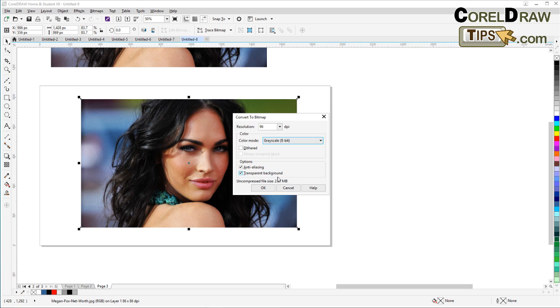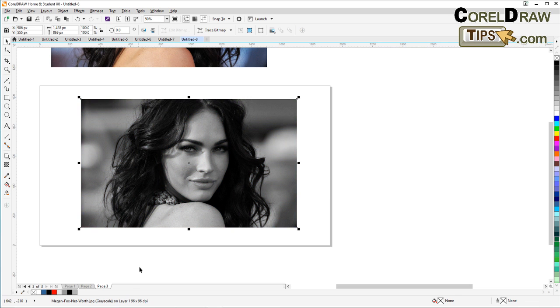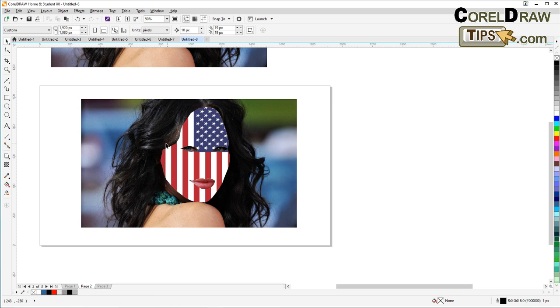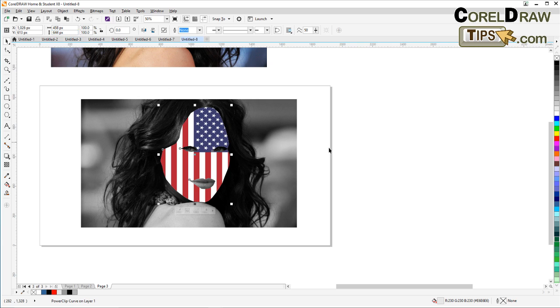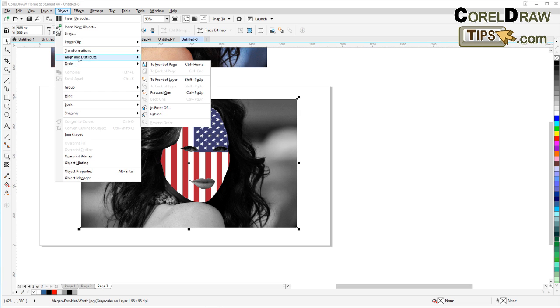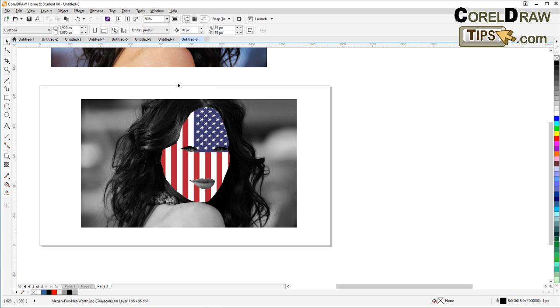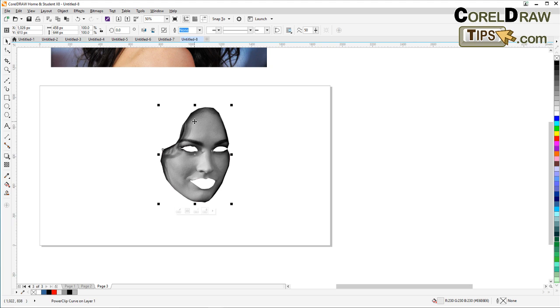But then I'm going to make this grayscale, like you said. Let's try that one. That's grayscale. But now I need the path of this, right? So I'm still gonna copy this. It's still a vector, so I'm gonna copy and then go back in page 3 and then paste, and then I'm gonna click the grayscale, and go to object, power clip, place in subframe, and here, right?